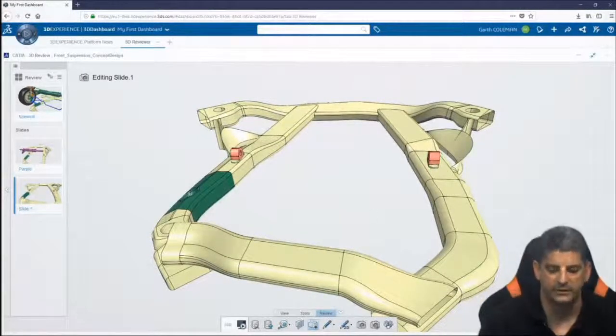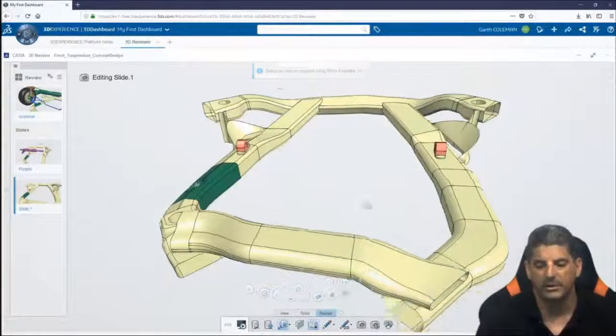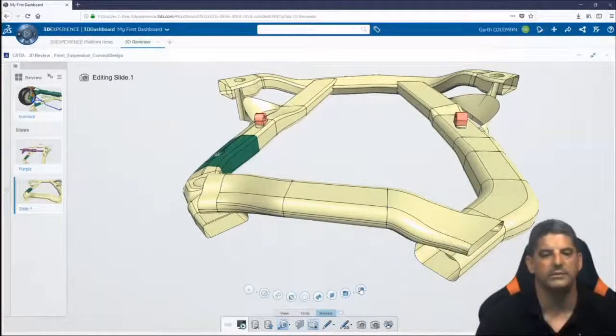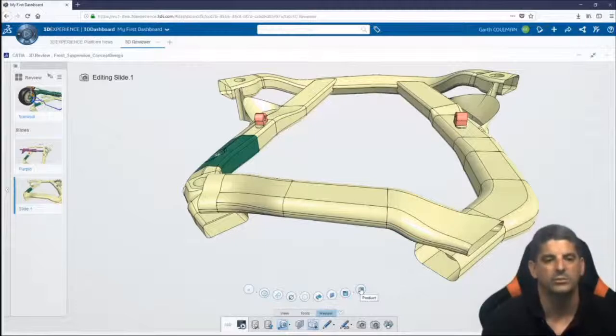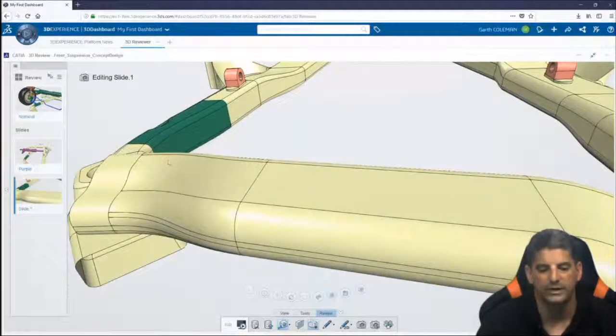So, a couple of dimensions. Let's take a look. When I click on this, I can do a thickness measurement or a measurement with a little, you see, a little ruler there. Now, there are a bunch of ways to select. This is very similar to the measurement tools in Product Explorer and Product Editor, where you can control what it is you're selecting. So if I were to select, say, this one here, which is planes, now you'll notice it's only going to allow me to select planes. So this curved surface here, I can't select it, but there's a plane. I can select that. All right?